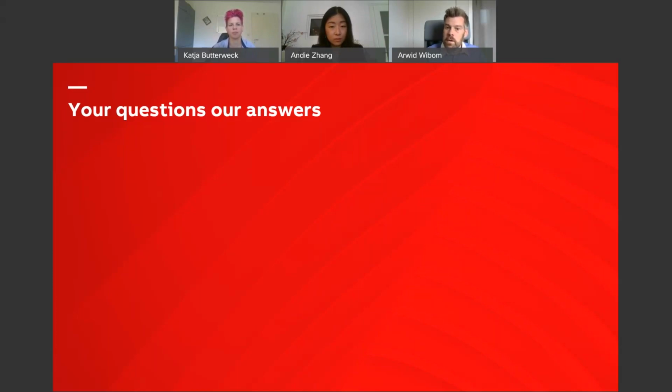Perfect, thank you. And I think we touched upon this, if it's possible to use ABB Vision with other cameras, such as Intel RealSense. Yeah, so you just need to have the interface and then it's possible. But not in integrated vision. So are the packages, the functions for Vision included in RobotStudio without additional licenses? If you buy a dual arm Yumi, it's included. If you buy the single arm Yumi with a hand camera, it's also included. If you buy an industrial robot, you need to select the option integrated vision.